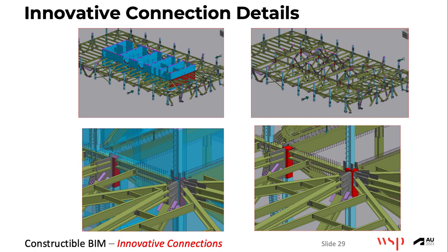The first thing I learned is that there's such a thing as a forging. It used to be castings; now it's a forging. This is solid steel in red. So you don't have to infill a member with stiffeners and doublers and try to weld everything together, and then find out, by the way, those of you who are not in the business, usually a surprise, that steel cracks.